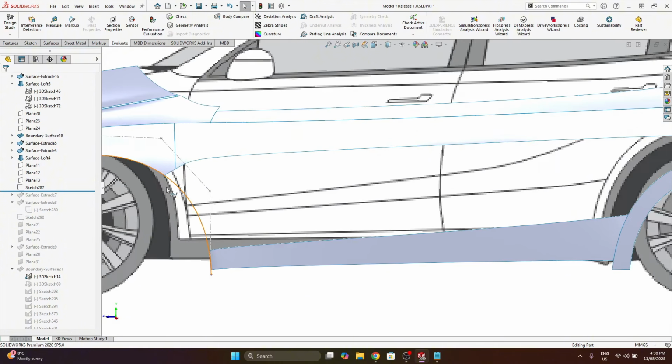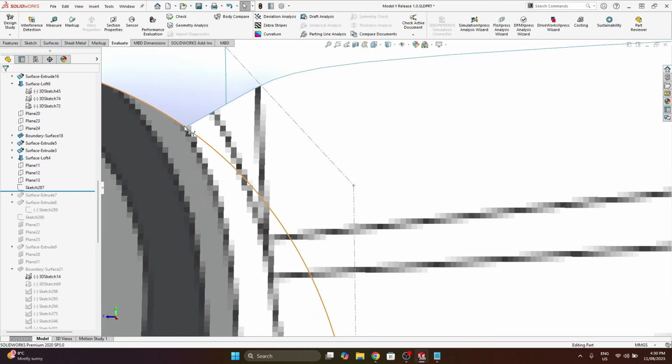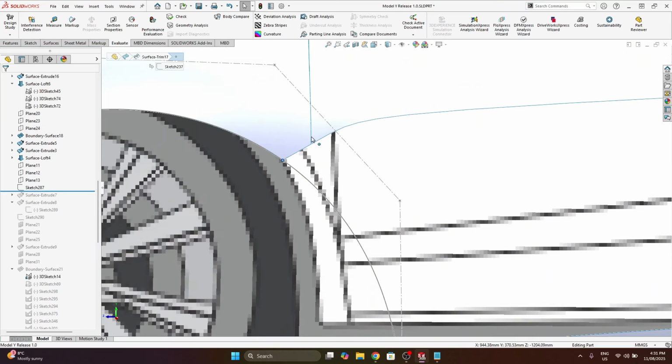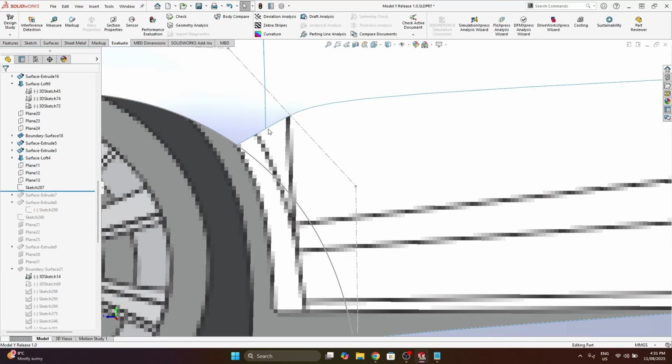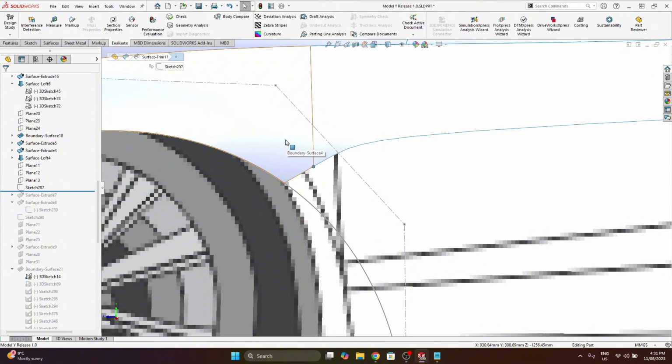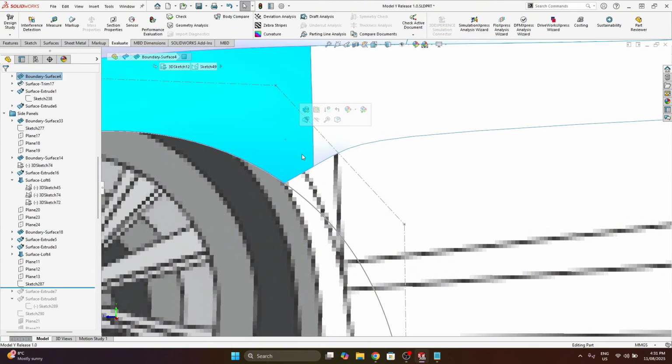that I plan to build in a single surface. I know from this region, roughly from this vertice up to this vertice, I want it to be tangent continuous. So if my intermediate guide curve running from this vertice can be set so it's tangent and curvature continuous to this highlighted face, that would help a lot and kind of be necessary.